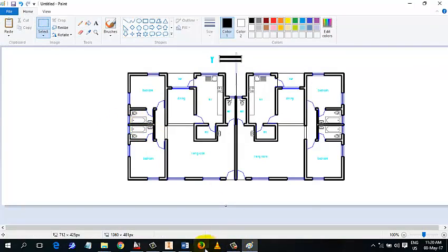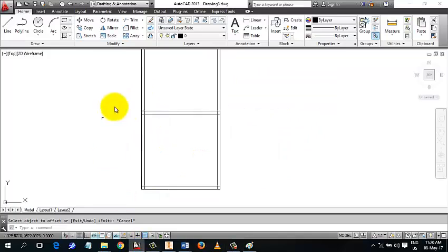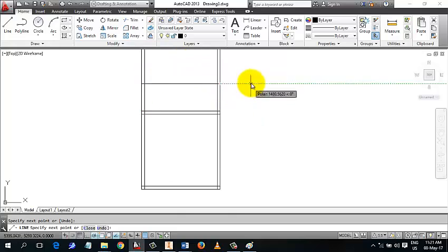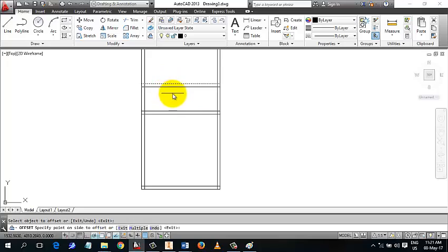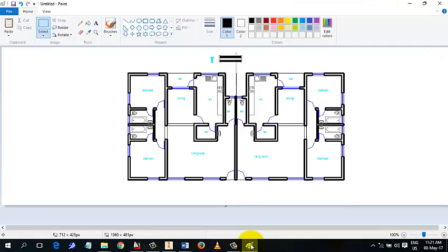The next thing I'm going to do is the wall of this toilet, the wall of that toilet. So go back to AutoCAD, then start the line command. Let's start from here. The toilet is 1,200, but plus the 150 wall, there are the 1,350. Enter there, then bring it here. Then I will offset, then enter. It's going to be inward, I mean? Okay, good.